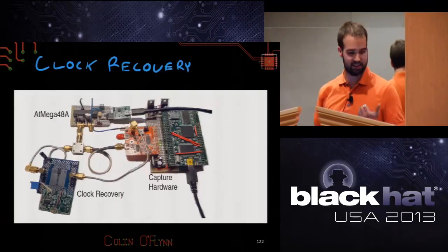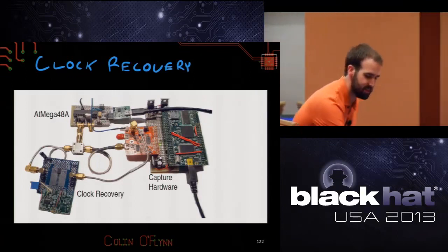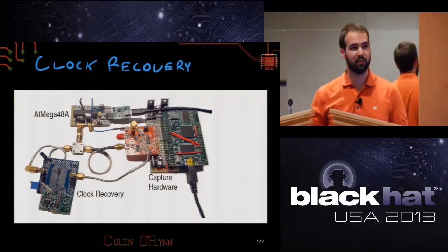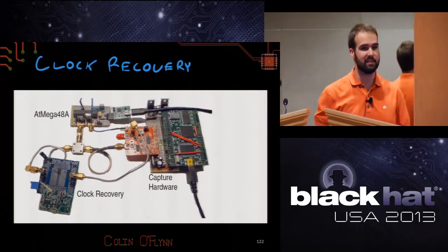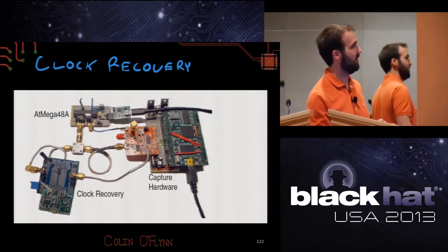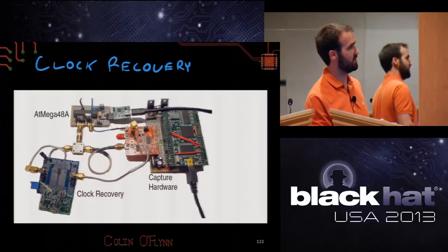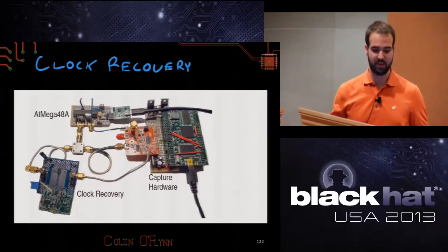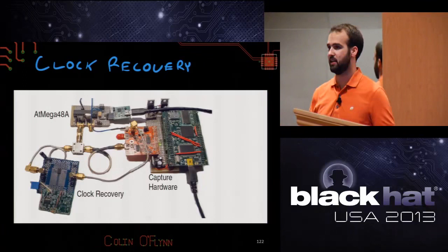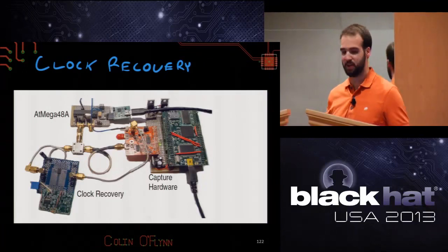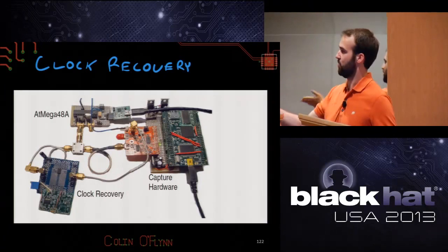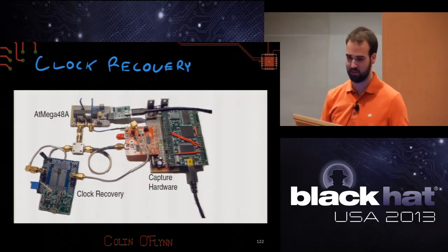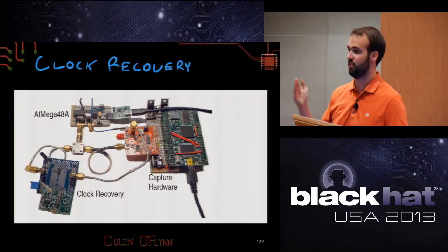So number one is I always assume you have the clock. This is pretty safe to assume for a lot of digital systems. Not all, because some systems may have internal oscillators inside the chip stopping you from tapping it. You can use a clock recovery system. I won't go into detail, but it's almost exactly like it's done in communications electronics. It's been known, again, 20, 30 plus years, this sort of idea. You can use that to recover the clock and then attack the system, and this works quite well, even if the clock changes during operation.